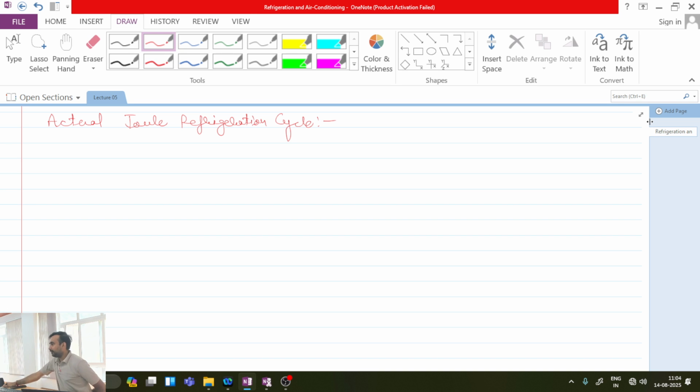In a similar way, whenever we make the assumption of isentropic compression and expansion processes inside the turbine and the compressor, we assume that there is no entropy generation. However, in actual processes, there is some amount of heat exchange, because even if you put a significant amount of insulation along the body of the compressor or turbine, there will still be some heat leakages because insulation cannot be 100% perfect.